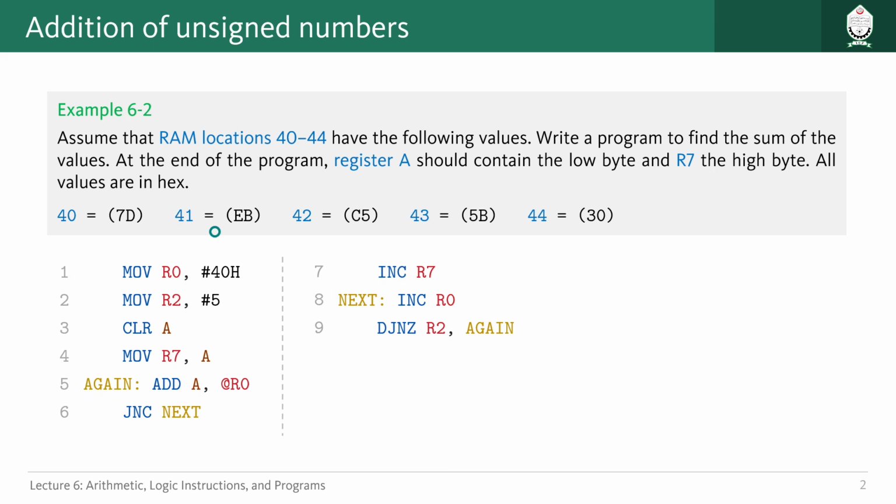Okay, so here we are asked to add multiple hexadecimal values together, and we have seen examples like that whenever we have multiple values to add. How we actually deal with that in 8051 is, because these values are 8 bits, whenever we add multiple values the result can exceed the 8-bit bound, right? So what we do, we basically add two values at a time. So maybe for example here we can add the first two values, 7D, and then with that EB. If we add the two values, then maybe there can be some carry there.